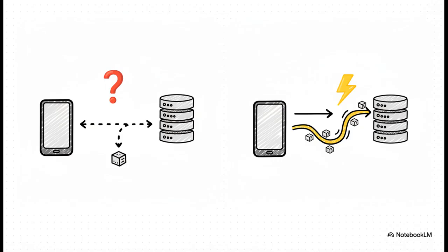So how do you get these VQTs? Well, for a simple pull, an application can just send a POST request to the /object/value endpoint. Easy. But for real-time data, i3X uses subscriptions that push updates using server-sent events. It's a simple, standard way to get a live stream of values. And for those of you dealing with complex, nested objects, there's a handy max depth parameter to control how deep into a compositional hierarchy you want to go.